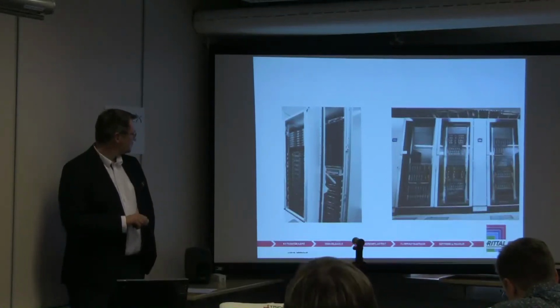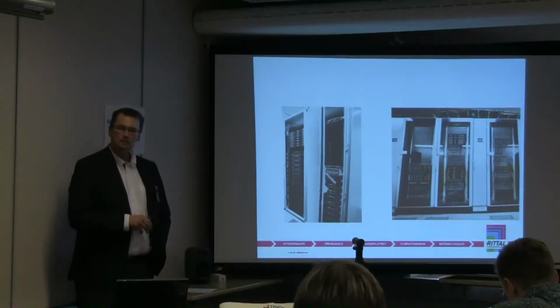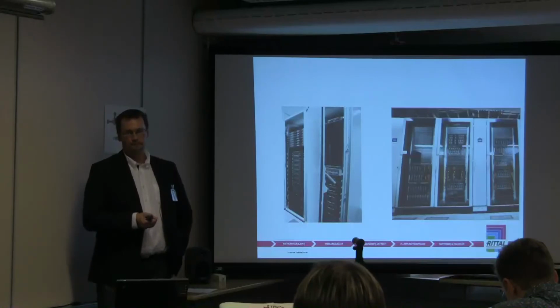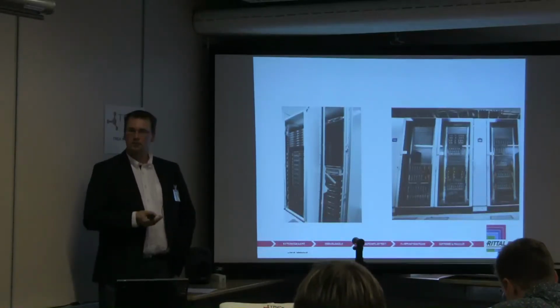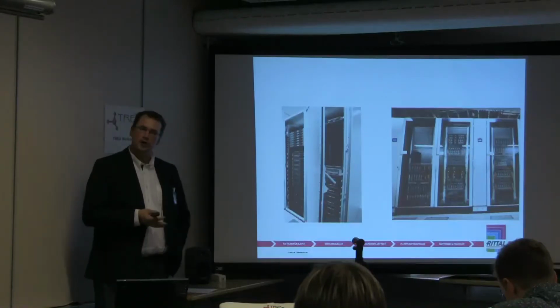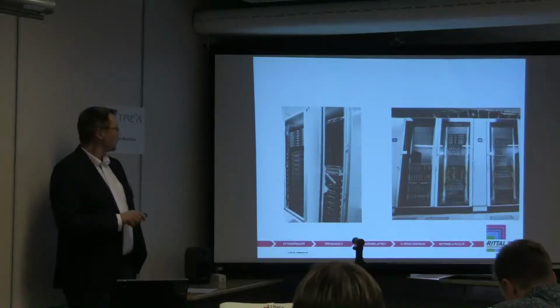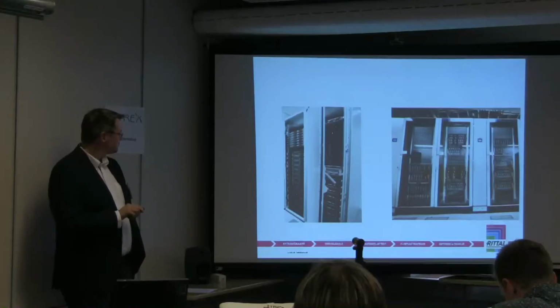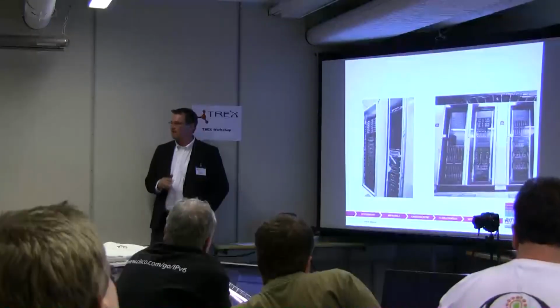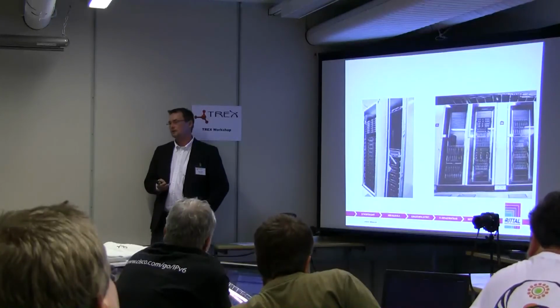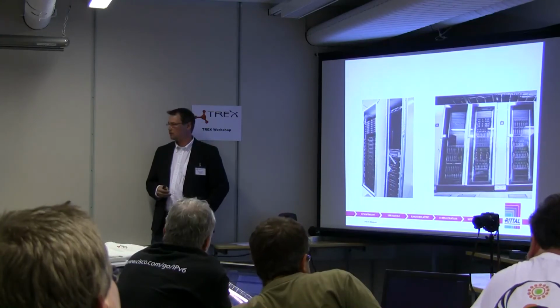We have servers and other equipment, and all the empty units are open. So basically, the cold air that we provide inside the data center to cool down the devices will go through here, because there's no pressure loss. Of course, the servers have fans that suck in the air, but air also goes through here, so that will reduce our cooling power.